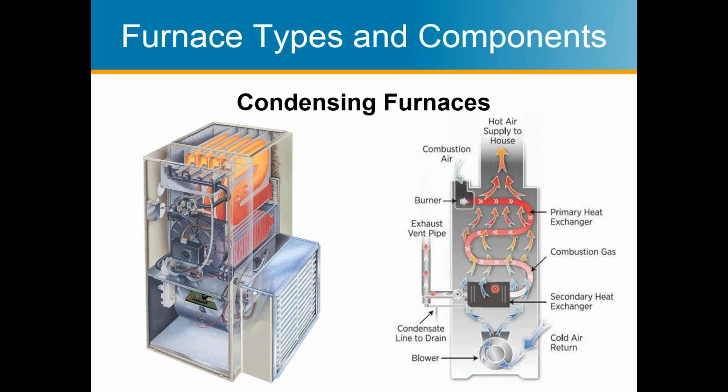And so that's what the condensation is going to come down here. But the exhaust comes, the burners are at top, the exhaust comes out at bottom, and then it's going to exhaust out of the building. So here, same thing, the burners are up top. This is a more typical heat exchange pattern that you'll see where the heat exchangers, the flames are shot inside, the exhaust gases and the heat circulate down.